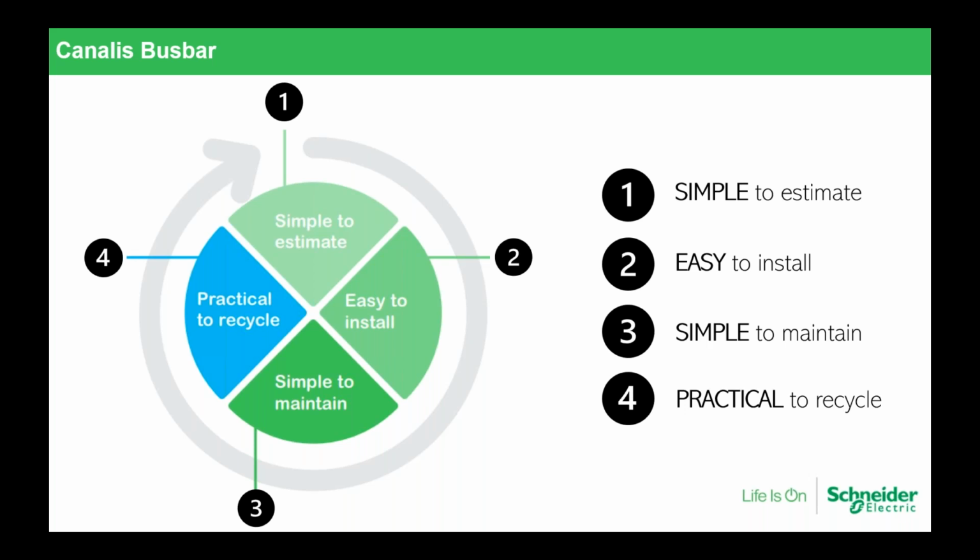No maintenance is required on the Canalis electrical contacts. So this is very good to know. It's kind of fit and forget, because you don't need to go and verify electrical contacts as you need to do for cables. For instance, with aluminum cables, we know that over time the connection could loosen, and if this happens on the neutral, it means you can have over or under voltage.